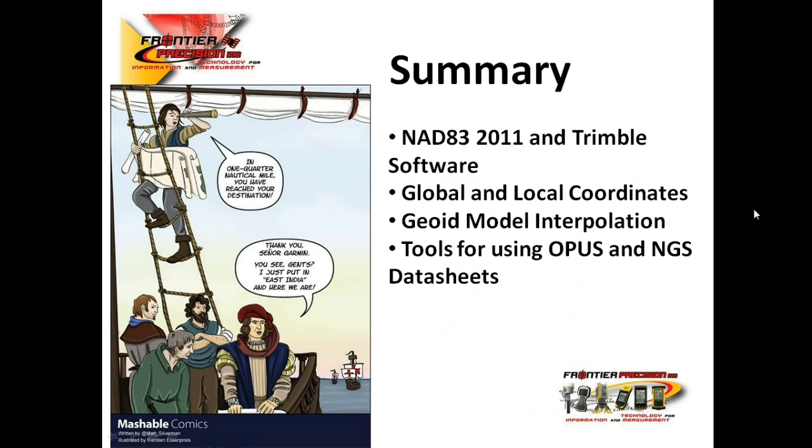So to summarize today's session, we discussed NAD83 2011 and the Trimble software, and some of the workflows and what's happening. And that brings us to the point about global and local coordinates, how important that is. That becomes very important when using the NAD83 2011 designation. Make sure that you're editing your local values and not your global values. I hope you can take that away from today's session.